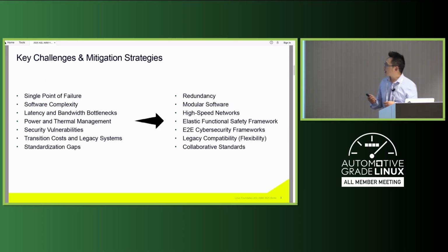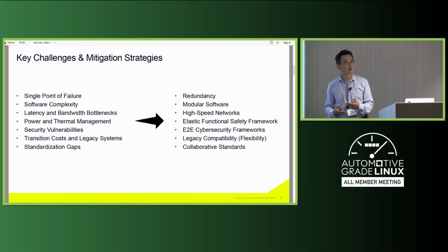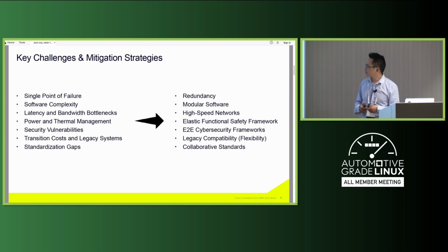So when we design new software to support a new EE architecture, you have to be mindful that with the introduction of the new software, the legacy parts, the radar, the sensor, the legacy counterpart ECUs, will stop working or cannot be OTA'd anymore and cannot be diagnosed anymore.